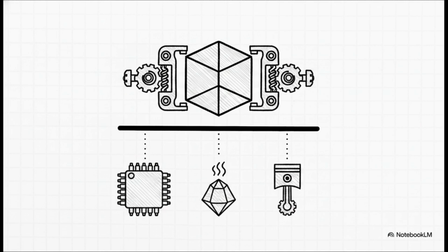Layer 1 is the physical layer. What's absolutely brilliant here is that CSDL is entirely hardware independent. Whether you're working with CMOS circuits, photonic arrays, piezoelectric actuators, or even high-fidelity Python digital twins, it just works. We simply map a state vector to a physical node's analog voltage, pressure, or temperature, and a control vector to the tuning voltage applied via a digital-to-analog converter.